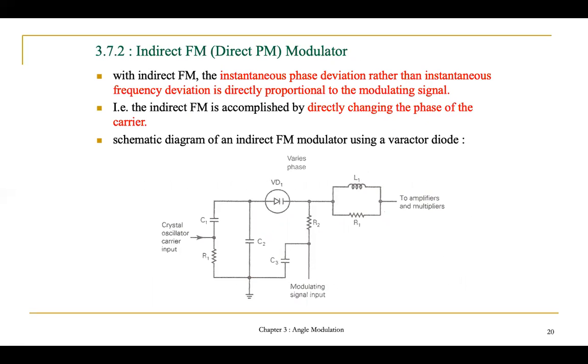So next, let's look into indirect FM or direct PM modulator. We know that if you have a PM modulator and you add an integrator in front, you will actually have an FM modulator. So that's why we call this an indirect FM modulator.